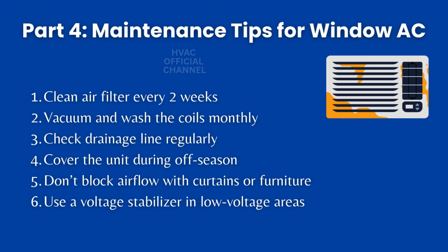Clean air filter every 2 weeks. Vacuum and wash the coils monthly. Check drainage line regularly. Cover the unit during off-season. Don't block airflow with curtains or furniture. Use a voltage stabilizer in low-voltage areas.